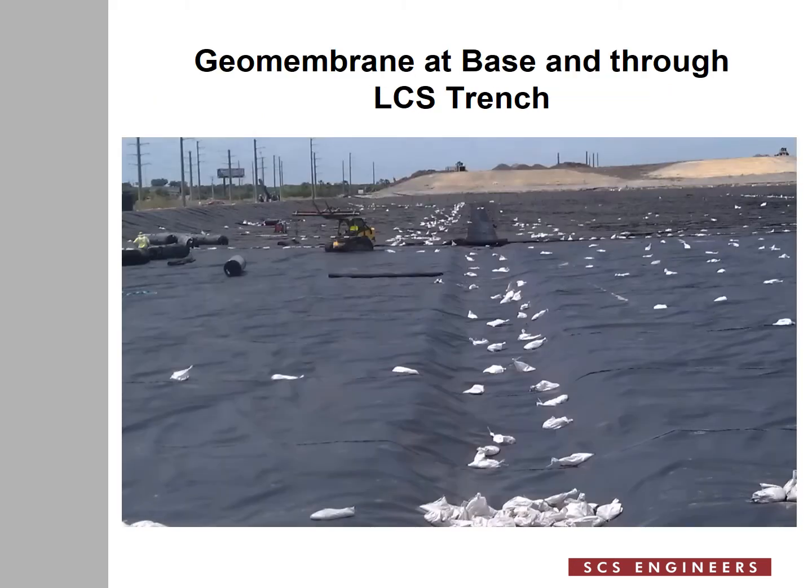Now we go through the photos of a construction event during which an innovative design was implemented. We start with this photo that showed the geomembrane at the base and through the trench. For a moment, just ignore the background and just pay attention to the front, that the geomembrane is laid out, deployed, and the next step is to install the geocomposite.